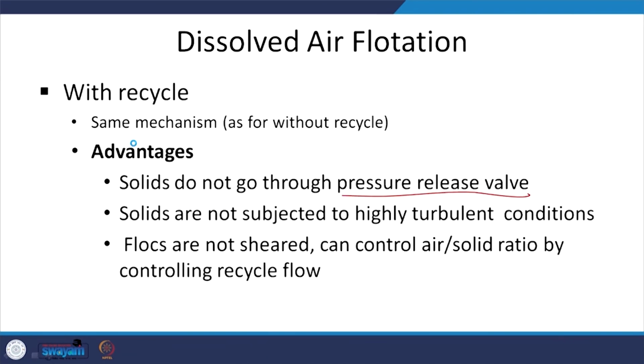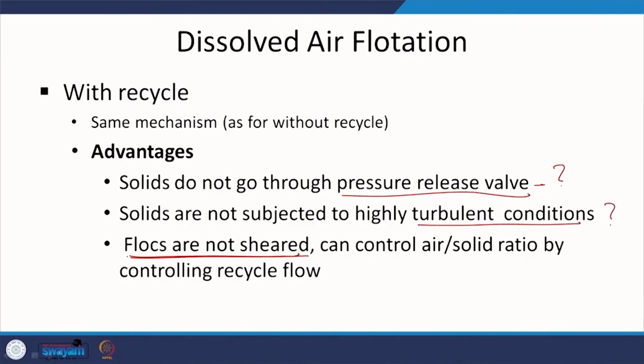So, now let us look at the advantages. Solids do not go through the pressure release valve. So, why is that an advantage? Because of that there are no turbulent conditions. Why is that again important? Because then the flocs are not sheared, right. So, this is the relevant aspect, flocs are not sheared. Again, if flocs are sheared, you are going to have issues with respect to thickening. So, the flocs are not sheared, let us see, right. So, that is not affecting thickening with respect to separation and being taken up, right.